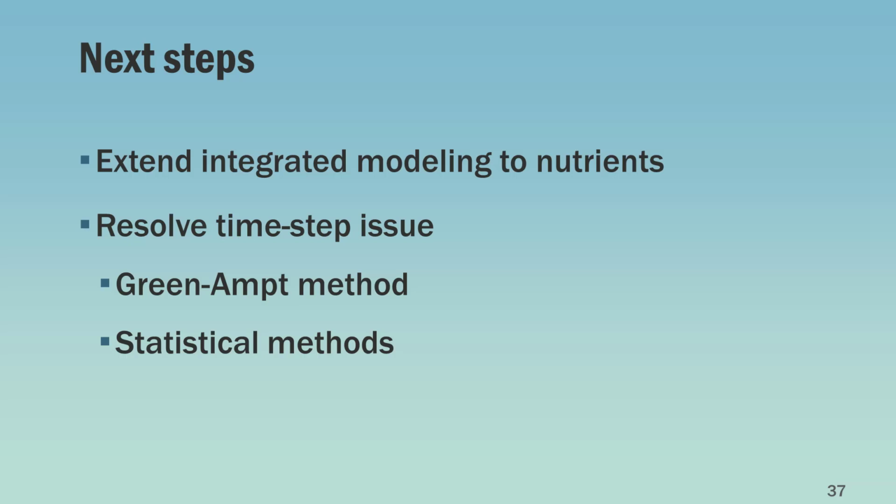Unfortunately, we are constrained by the resolution of the SWAT model, which generally produces outputs at the daily time step if using the curve number method. Of course, the Green-Ampt method can be used to generate water loads at the sub-daily time step, but again, we are still facing the issue of sediment loads being generated from the SWAT model at a daily time step. So we somehow have to resolve going from a daily to a sub-daily time step.